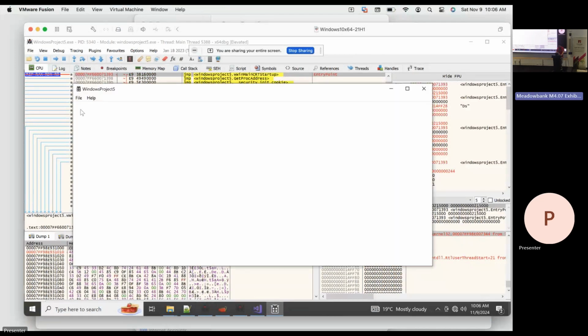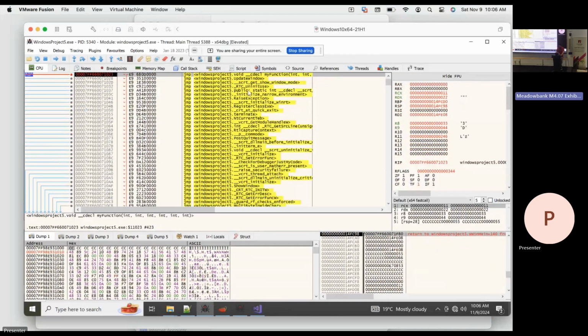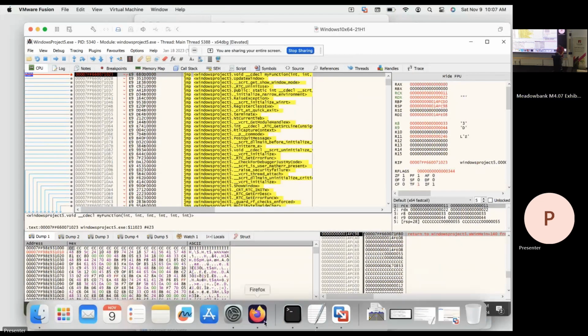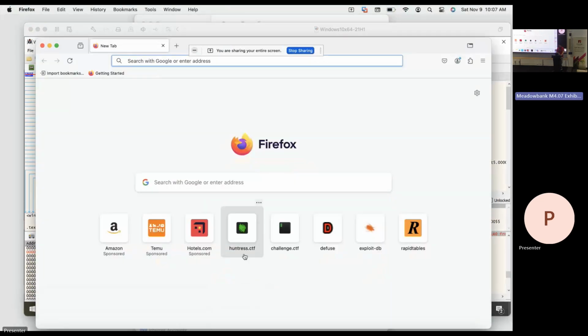And it should hit the breakpoint there. Okay, we hit the breakpoint on the function that we made, and let's check. Parameters are being passed here, here, R8 and R9, and as you can see, we have these 5 and 6 on the stack. So that's it for me.